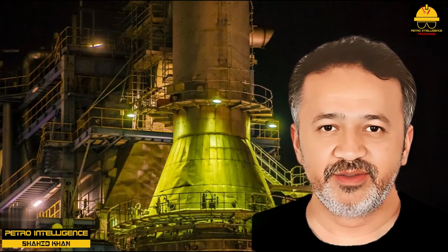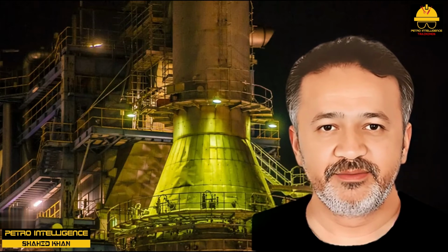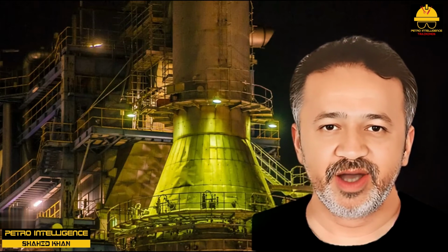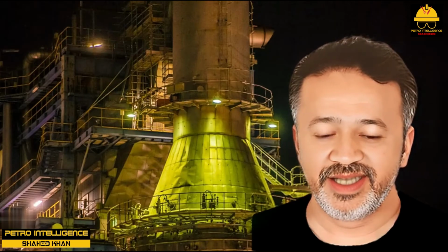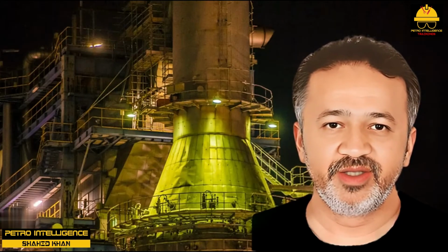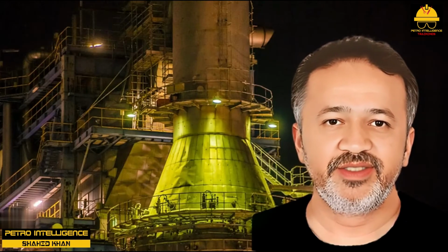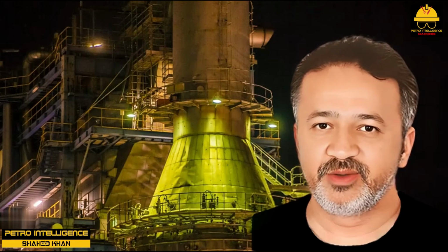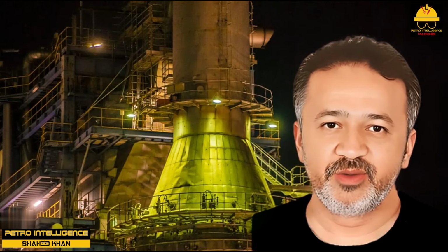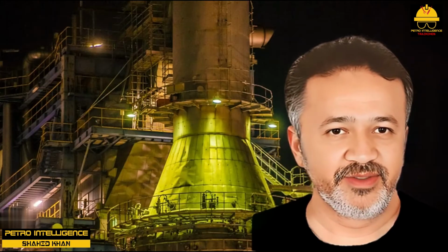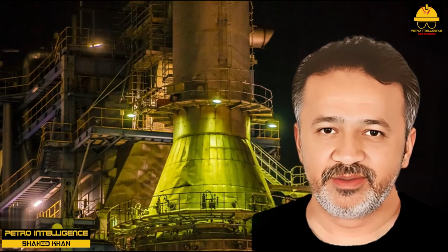A certain amount of air leaks in through the convective section and stack from outside the heater. When these hot, combustible hydrocarbons in the form of unburned fuel mix with the extra air that is leaking in from the environment, reignition is liable to occur. We call this afterburn, or secondary ignition, meaning there is now fire in the convective section. When combustible materials or unburned fuel reignite in the convective section, a dramatic increase in flue gas temperature will occur.